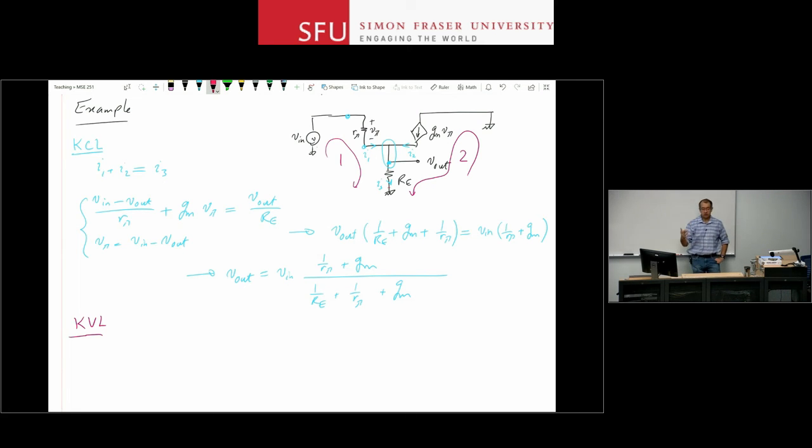It's like the current to a voltage source. An ideal voltage source can provide any current that the circuit needs. And same thing here. An ideal current source, which we assume this one is, can sustain any voltage drop across it. So in this case, maybe a KVL on the right loop doesn't help me much, but let's just go through the example and we'll see that we actually can solve it just with the equations from the left loop.